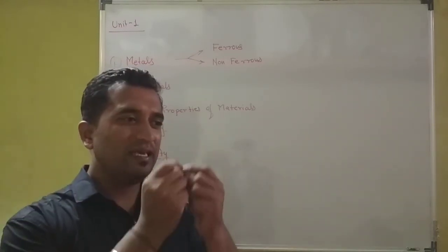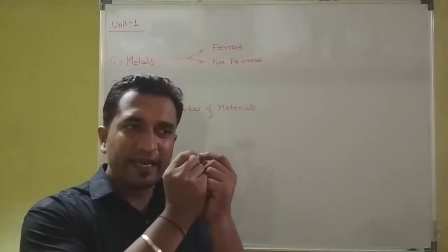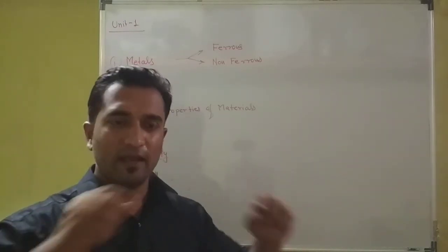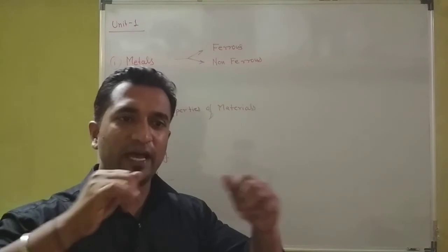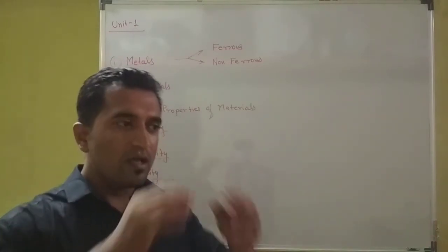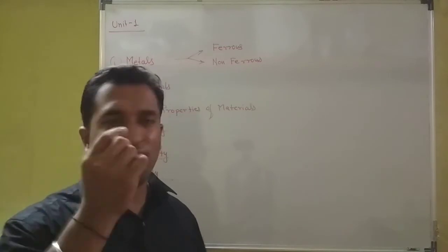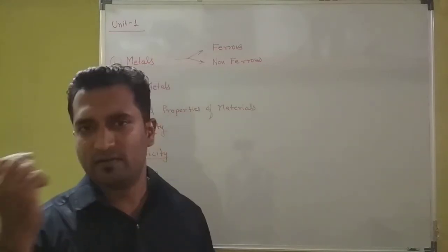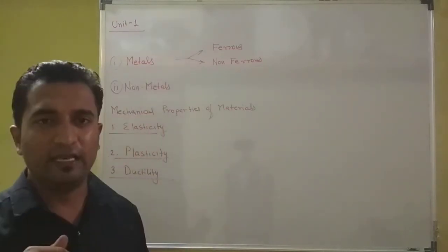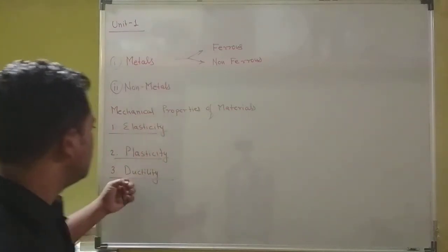But you can see the thickness of that material is getting reduced. It is not getting deformed easily. First it is getting reduced, then after some limit it will get deformed. That reduction and forming a thin wire, that property of material or metal is called as ductility.